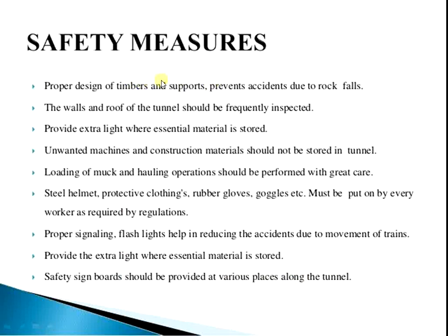Then what are the safety measures? The proper design of timbers and supports prevents accidents due to rock falls. We have to design the timbers and supports properly to avoid accidents due to rock falls. The walls and roof of the tunnel should be frequently and strictly inspected.